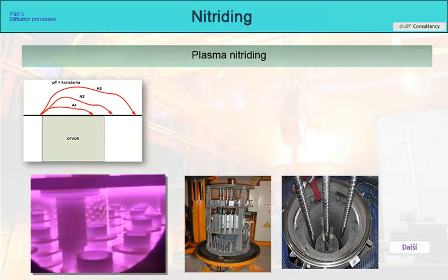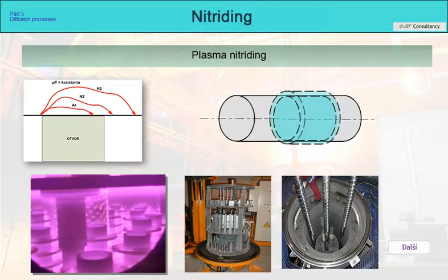However, the great advantage of plasma is the masking of surfaces that we do not want to nitride. A situation where we do not nitride surfaces where there is no discharge can be used. For example, we have a shaft, and on it is the surface that we want to have soft, without nitriding. We put a steel ring over the part of the shaft that we want to protect. It will be nitrided, but the shaft surface covered by it will be untouched by nitriding.